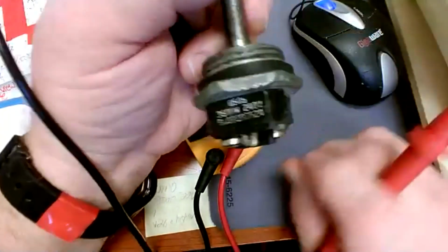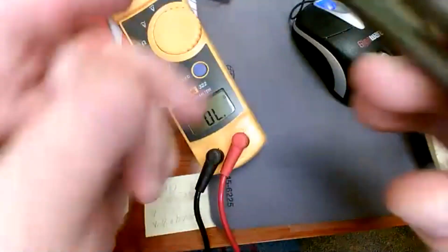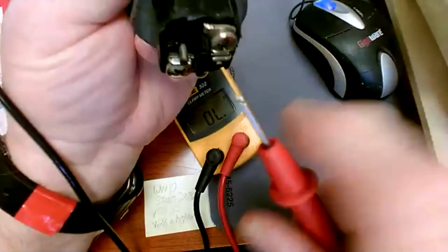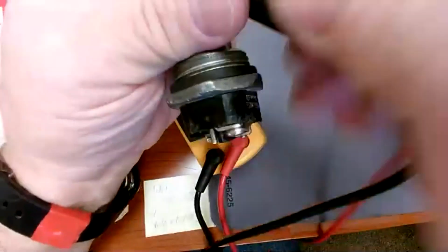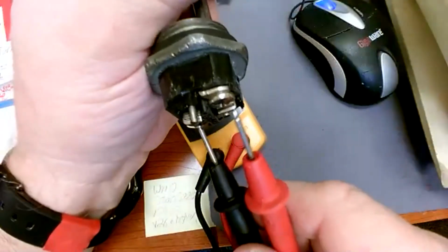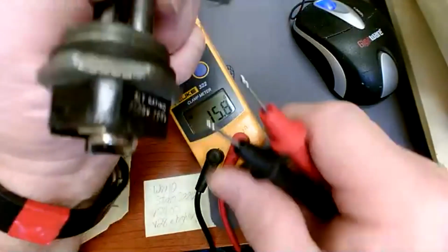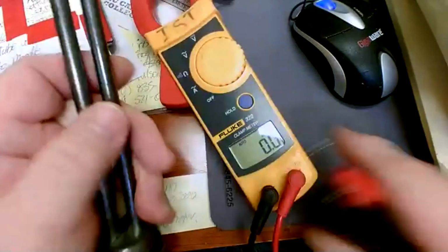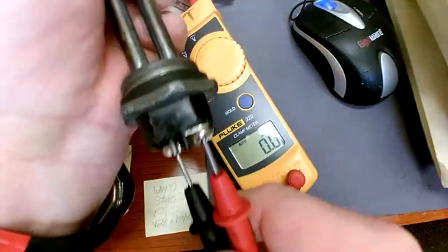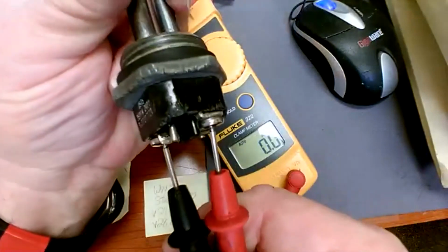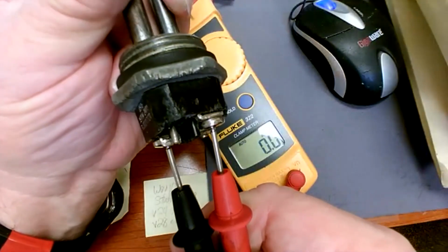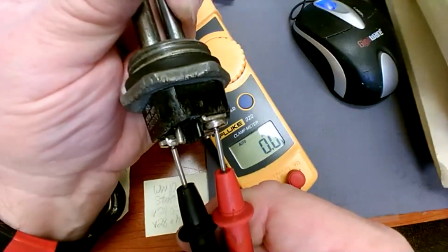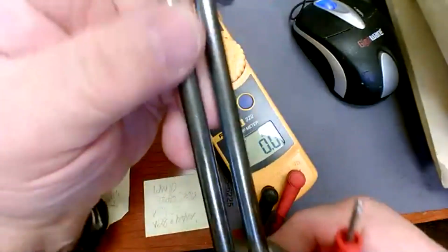So the reason for me showing you that is, if you're troubleshooting one at home, you would naturally go to it, and if your water heater is not really putting out properly, you would measure voltage, AC volts, as a matter of fact. Let's say you went to it and it did read 240 volts like it's supposed to, or somewhere between 208 and 240, and the voltage was actually there, but yet the heater element was not giving you any hot water.